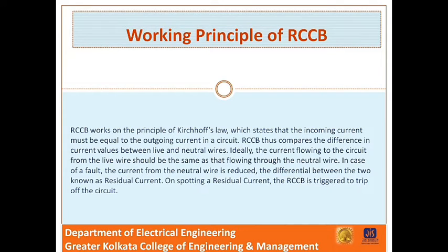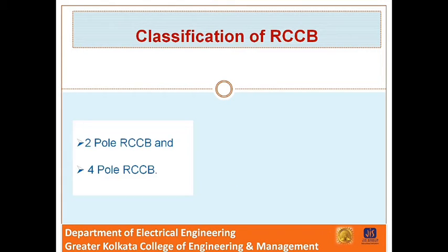A circuit including residual current devices has a test facility to check the reliability of RCCB. When the test button is pushed and the current starts to flow through the test circuit, it creates an imbalance on the neutral coil of the device, the RCCB trips and supply is disconnected, thereby checking RCCB's reliability.